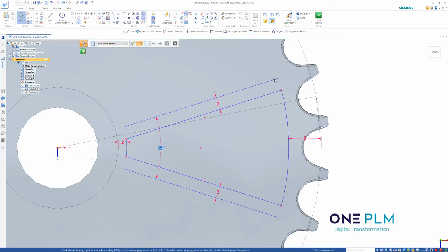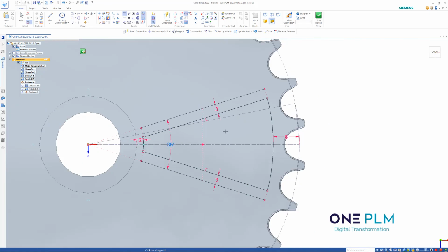And then we can connect the endpoint of that line. So we can use that connect and connect that to the arc on there and do that for each of these endpoint options on there. So if we choose the end of a line and link that to the arc at each point, we're then back to fully defined.